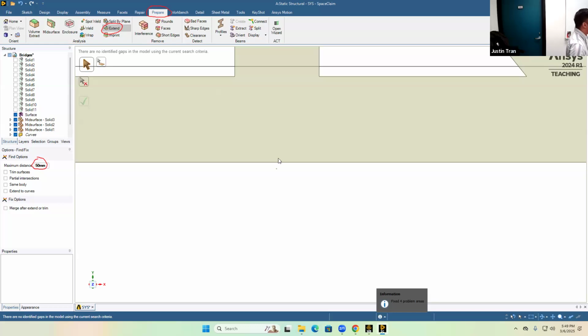They had their cross section, and so it wasn't really apparent that they were misaligned. But now that we've eliminated that cross section, we've eliminated that thickness, it becomes a lot more clear that not all of these beams were aligned properly. This could happen sometimes when you're doing these things. If you're using this CAD model just for visualization, something like this could be acceptable. But since we're running FEA on this, a small error like this is important.